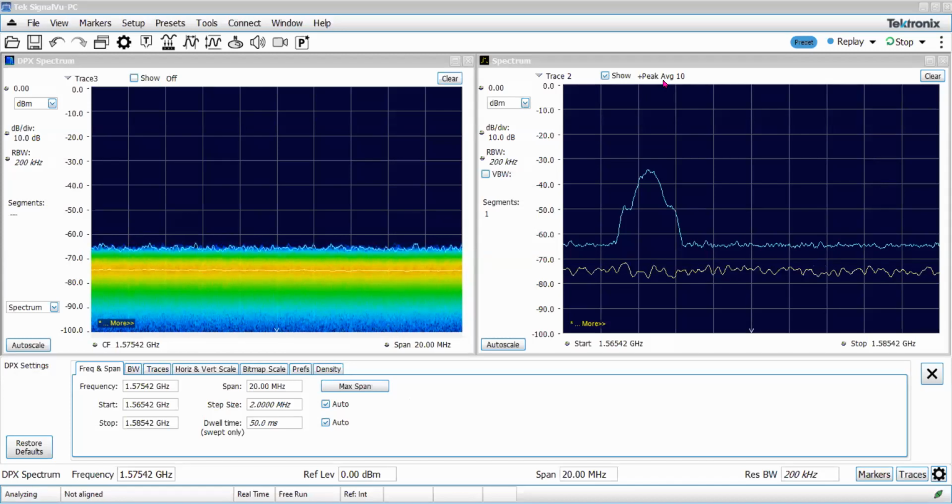But the signal generator, this one, you can buy much cheaper, around $300 to $500, so you can do some analysis. And this device that I'm using to generate the GPS signal can also be used as a spectrum analyzer, not up to this level of quality, but you can still do this type of spectrum measurement. So it's possible to do this.